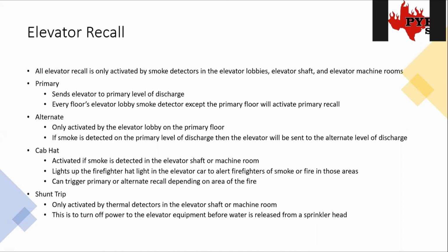If you're in a taller building like a mid-rise or high-rise, you might have to add some time to that. 45 seconds usually works pretty good for most buildings that are taller. But if it's really tall, of course, it's going to have to be longer, because it's just how long does it take that elevator to get there and open up. But 30 seconds most of the time is going to be all you need.